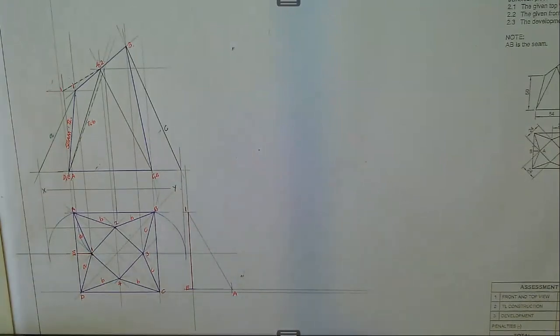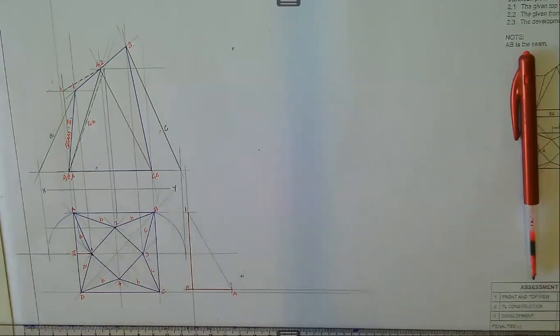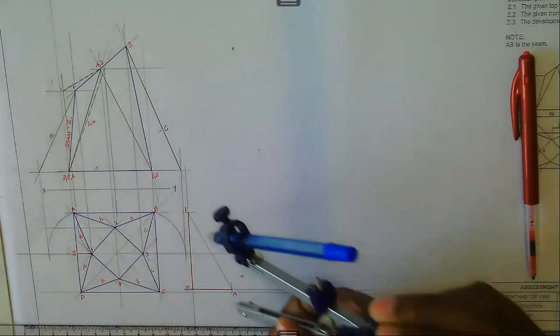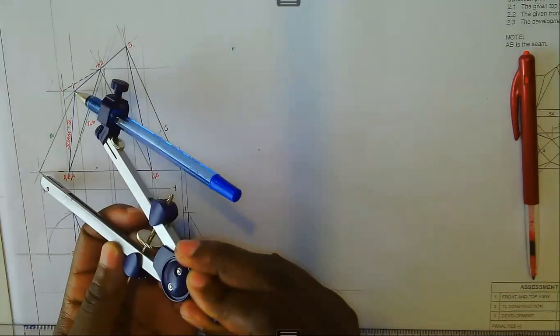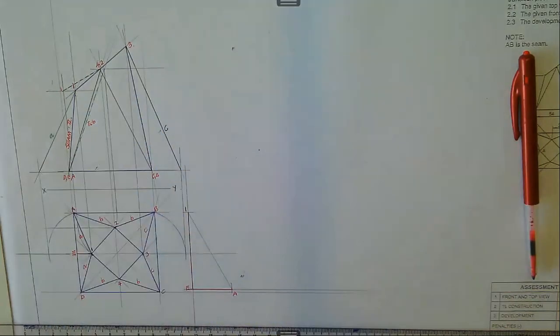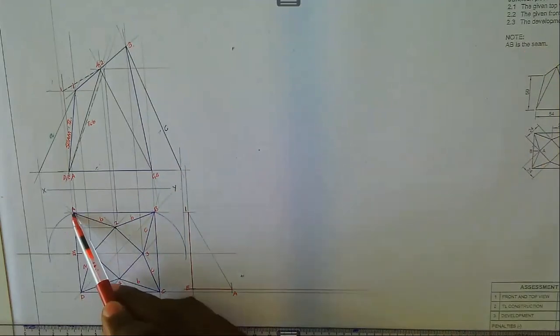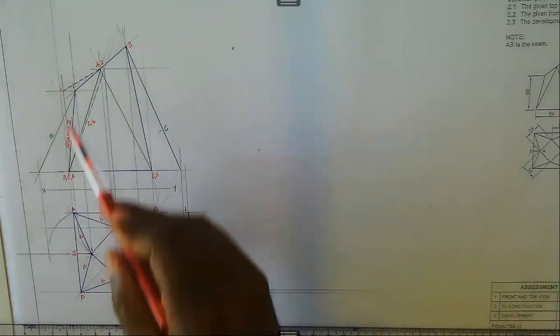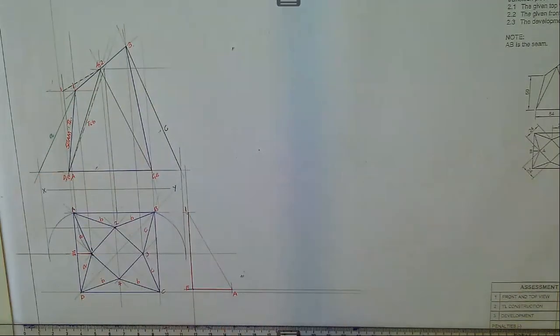So you can also outline this like that. Take this distance from here to there, go to this point, you would find that it's one and the same thing. Remember, you can also do the same thing from E to A and 1 to A, which is taking this distance, standing at point E, describe an arc, standing at point 1, taking the true distance from here to there, you describe an arc. It should still bring you that.